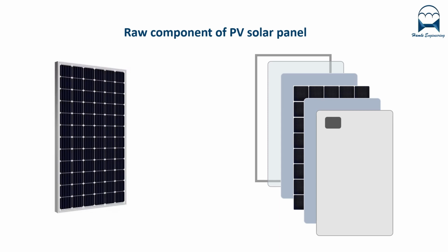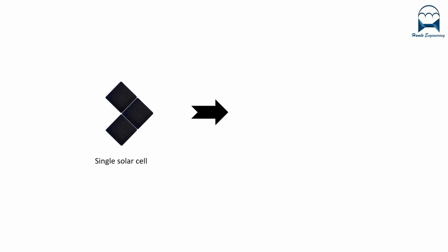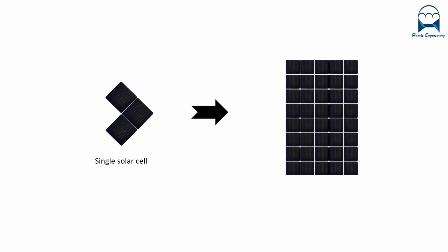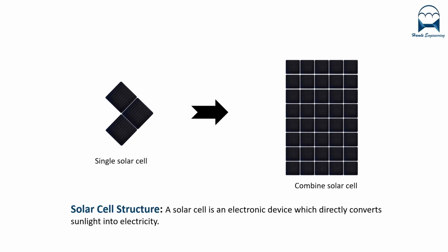Let's focus now on the single components more thoroughly. Photovoltaic solar cell. Cells are the main component and have the function to capture the sunlight and convert it into electricity. Crystalline cells can be monocrystalline or polycrystalline, according to their manufacturing process. This, however, does not affect the PV module production process. The main technical characteristics are size, color, number of busbars, and above all the conversion efficiency.